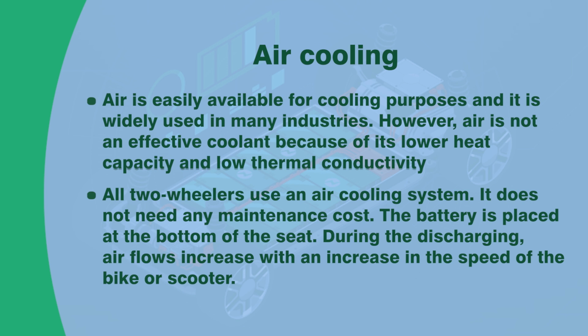However, the coolant effectiveness of air cooling is not too high, and as I said, the advantage is that there is no maintenance cost. In two wheelers, the battery is placed at the bottom of the seat, and during discharging, air flow increases with an increase in the speed of the bike or scooter.